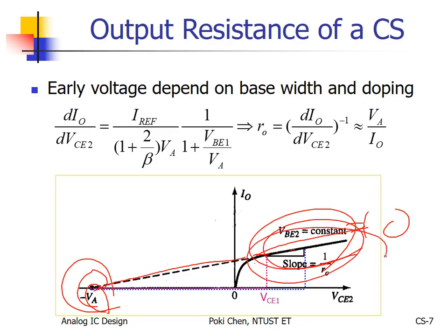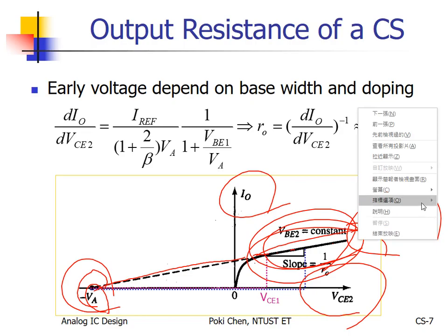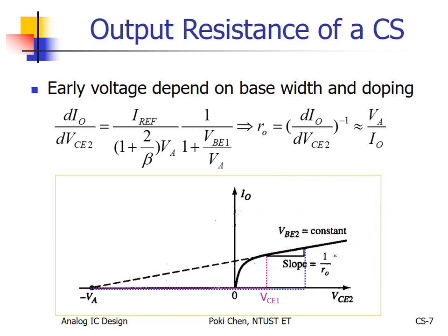Just think about this. For MOSFET, it is called saturation. What does it mean? The output current is saturated. Hopefully, it doesn't increase even if you increase the voltage, right? That is what we expect. But nothing is perfect. The slope is not 0. So we hope the larger VA, the better. But why do we focus on this?